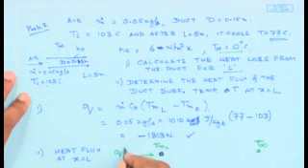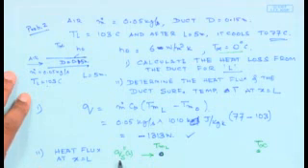So from 77 degree centigrade to 0 degree centigrade, the heat transfer is taking place, and the heat flux therefore is simply Q double prime S at location L. The double prime denotes the flux at x equals L, and it travels from a higher to a lower thermal potential. This T m at L is 77 degree and this T infinity is 0 degree centigrade.